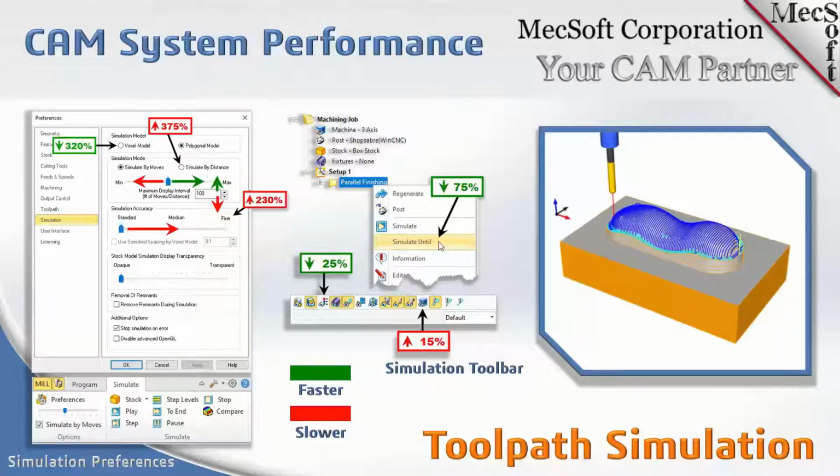And the voxel model has restrictions because it's dependent on the orientation of the tool. For all 3-axis and 2.5-axis, as Don mentioned, you can use the voxel model. But the minute you use different setups, as you might in a 4-axis setting or 5-axis indexed machining, then you cannot use the voxel model because you're coming at the part and machining it from different orientations.